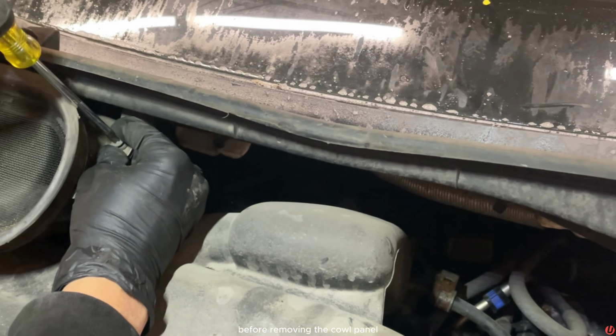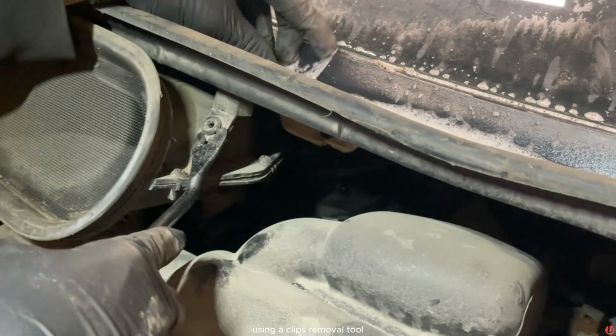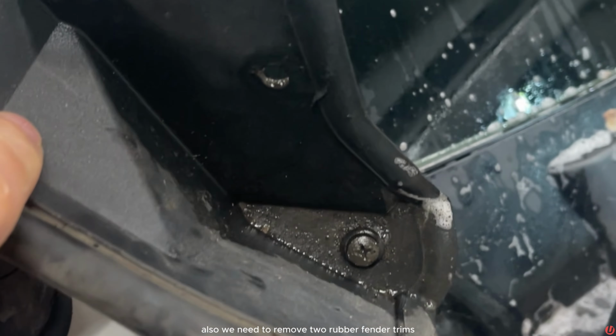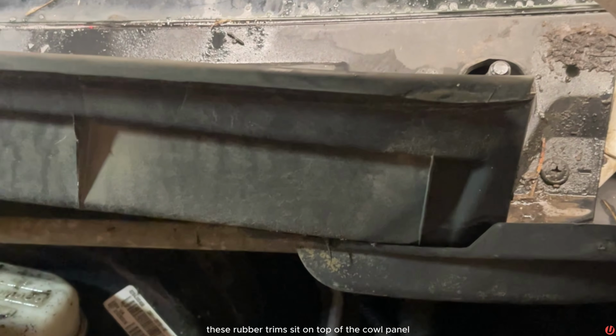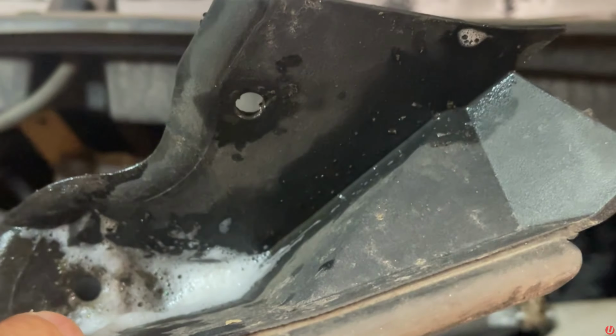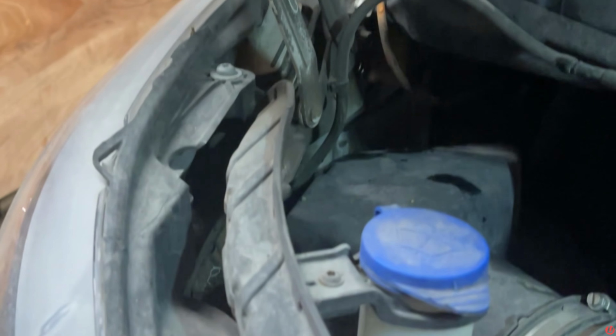Before removing the cowl panel, we will have to remove the 5 push pins that run along the cowl panel using a clips removal tool, also known as trim removal tool. Also, we need to remove 2 rubber fender trims on the driver's side and passenger side. These rubber trims sit on top of the cowl panel. Also, we will have to remove 2 push pins on the edge of the cowl panel on each side of the vehicle.